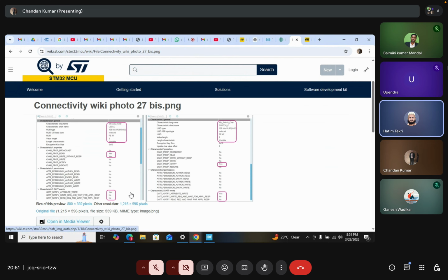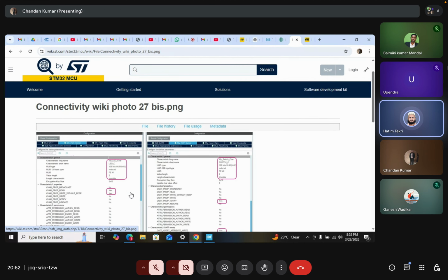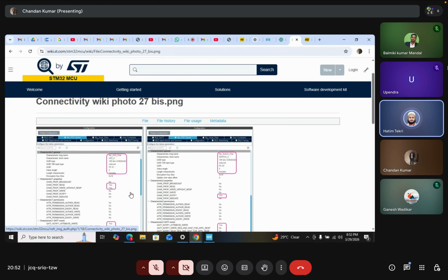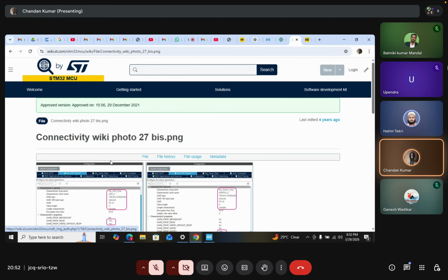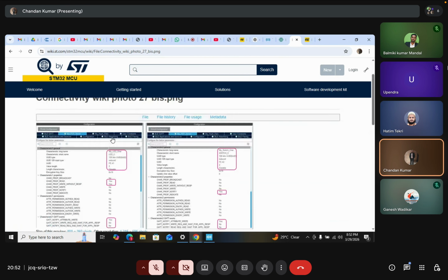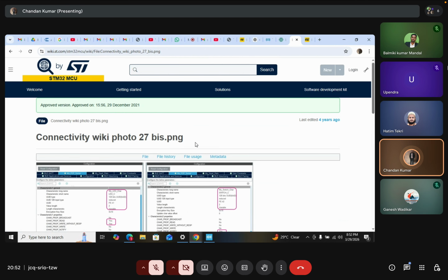Yeah, I have already told you, you will get this from the SIG UUID list document. There you will get all the UUID values, and below that list you will get all the encapsulated values. But how do we get the encapsulated value of our own UUID, which we have created? Just wait. I think you have not focused there. Let me show you.